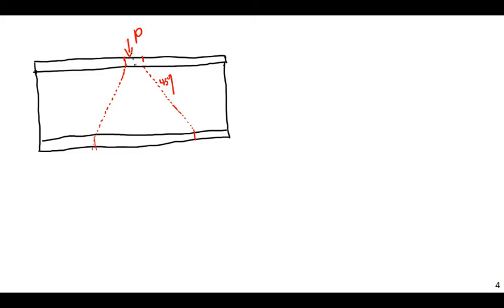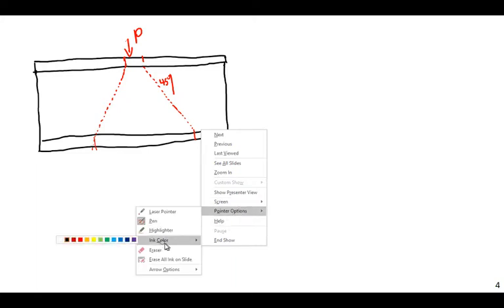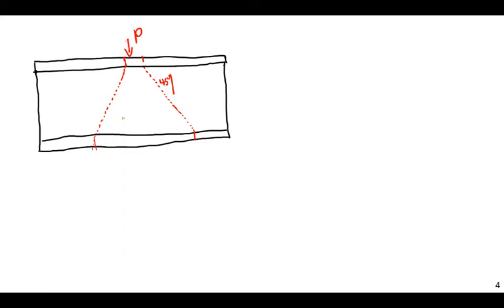The reason I'm illustrating this is, this is the only part of this beam that is actually experiencing any stress from the point load. Well, I shouldn't say not experiencing any stress. Obviously, the whole beam is going to go under bending. But in terms of feeling the actual vertical stress, or maybe I should say the shear, this is how it gets distributed throughout the entire beam. This portion of the beam is what actually ends up feeling the stress of that point load, and then has to distribute it to the rest of the member.